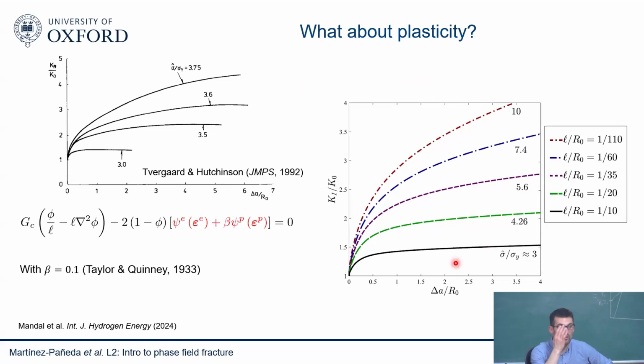And that also answers the other question that we were discussing before. What does fracture strength mean in an elastoplastic material, in a metal? Is it the grain boundary strength, or is it the UTS? Well, whatever it is, if you have experimental data like that one, you could actually calibrate your L to fit that experimental data, because the only thing that changes here is L. All the other parameters you know.